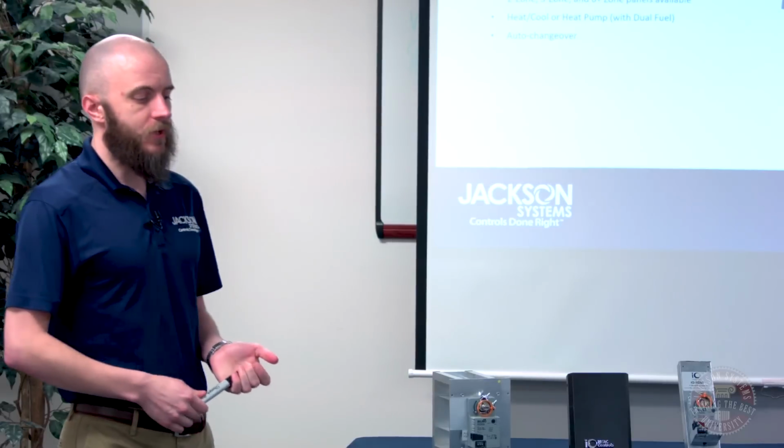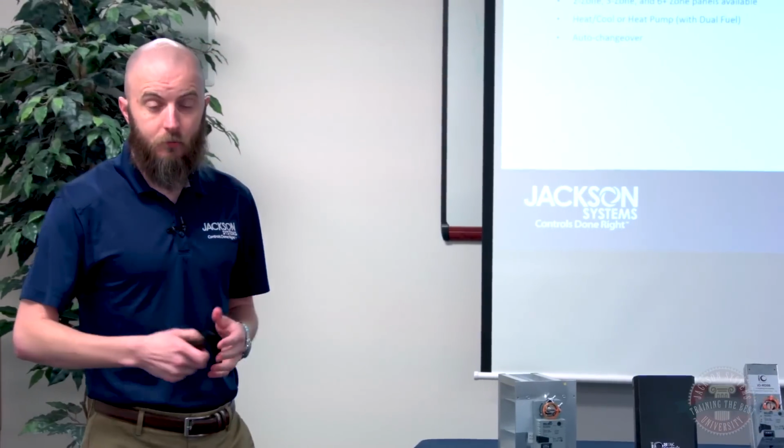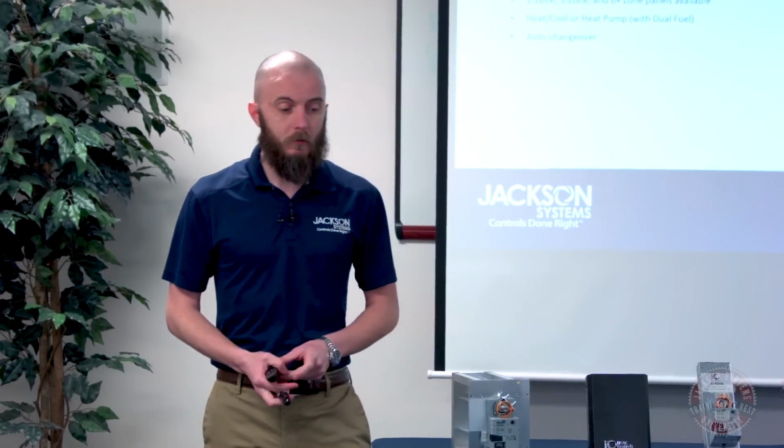You want to make sure you get a system that's compatible with what your system runs, so whether it's a heat cool or a heat pump. If you have a dual fuel system, you want to make sure you have a panel that can control that. Most panels have auto changeover now, so they can deal with receiving conflicting calls from thermostats. If one thermostat's calling for heat and another calls for cool, most boards are going to be able to handle that these days.